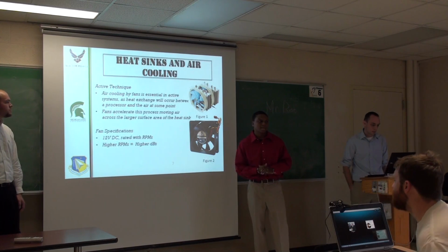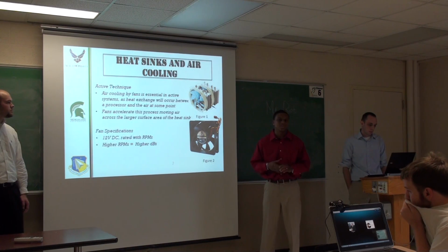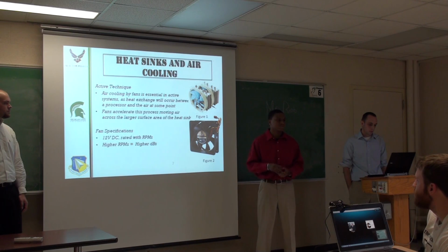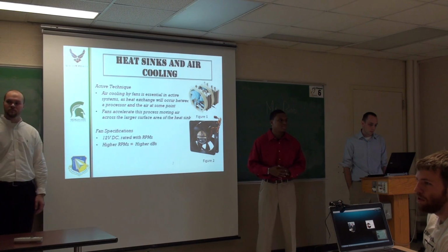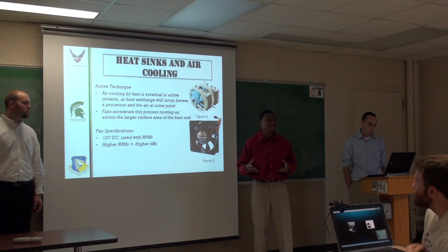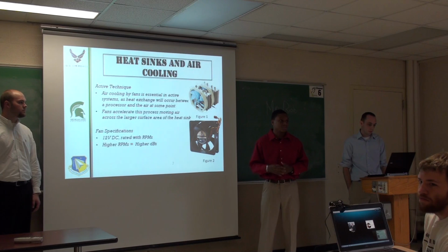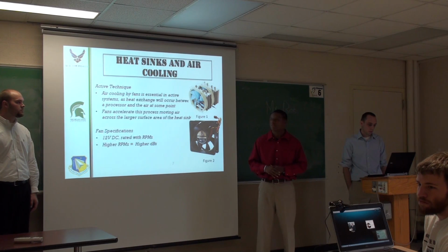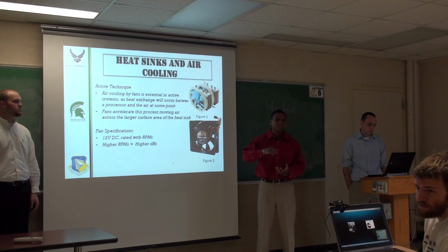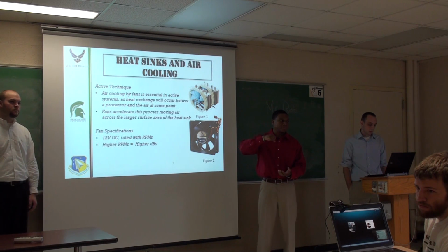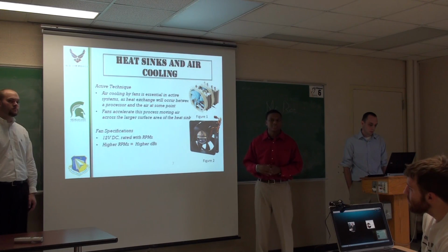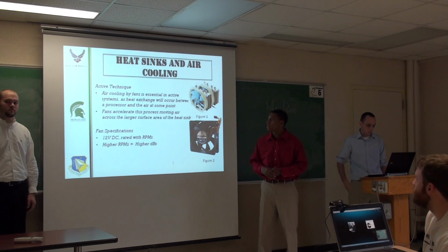The next technique is active cooling. So what this idea is, active cooling is used when your heat source generates a whole bunch of heat to the point where your heat sink is not able to actually conduct it at a rate that's efficient for the use of that electronic device. So you attach a fan to the heat sink, and essentially the fan sucks the heat away from the heat source at a faster rate in order for you to be able to cool that, let's say, microprocessor.